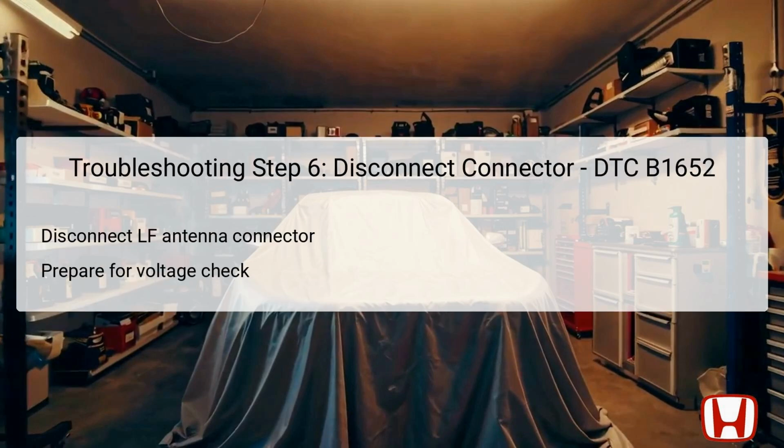Next, the procedure dictates disconnecting the right sliding door outer handle LF antenna 8P connector. This action is critical for being able to perform a voltage check later on, as it isolates the antenna from the circuit. The 8P connector is an electrical connector consisting of 8 pins, which ensures compatibility with the wiring system of the vehicle.